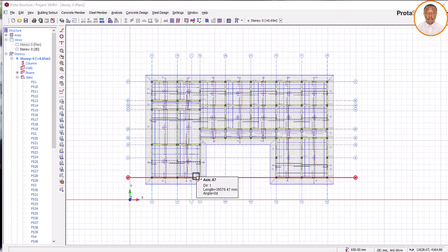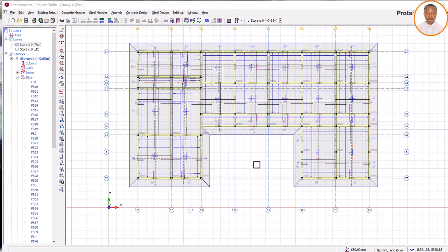Till I see you next time in our next video on part 2 of this beam raft design, how to correct your beam raft failure, part 2. We have done part 1, whereby we have seen that the total load of your structure is more than the bearing capacity of the soil, and how do you correct it? That has been done. You can now see that based on the geotechnical report, the 48 kilonewton is sufficient because of this cantilever slab we have provided around the beams. It is sufficient to carry this structure. There will be no failure when this structure is being carried out. So you have known how to correct your loads when the load of your structure is more than that of the soil. What can you do? How do you solve it? This is what we have done.